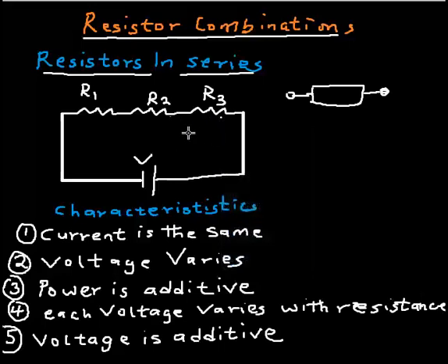This is a series connection, and one of the things that lets you know that resistors are connected in series is that the same piece of wire connects them. There is no branch. That simply means that the current that flows through those resistors flows without branching.